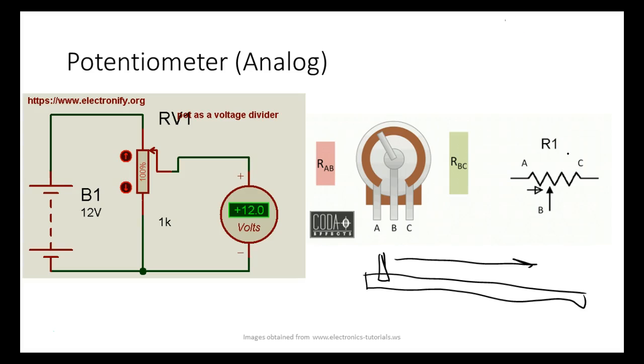It's a gear assembly that takes a linear motion and converts it into rotary, or takes rotary and converts it into linear. For years, guys, this is the way we drove our cars before we used hydraulics. A rack and pinion, because you turn your steering wheel like this, right? And then we have tie rods that went across that would do what? That would turn the wheels left to right. Go-karts still do it that way.